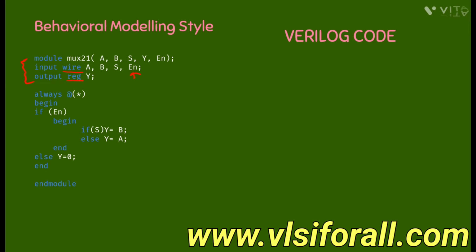The enable signal helps in switching on and off a digital entity. This means that when you switch on a particular entity using enable, you can use it, and whenever there is no use of that particular entity, you can always switch it off using the enable signal, and this helps in reducing the power consumption of the circuit. Hence, we should also know how to create Verilog codes which include enable signals.